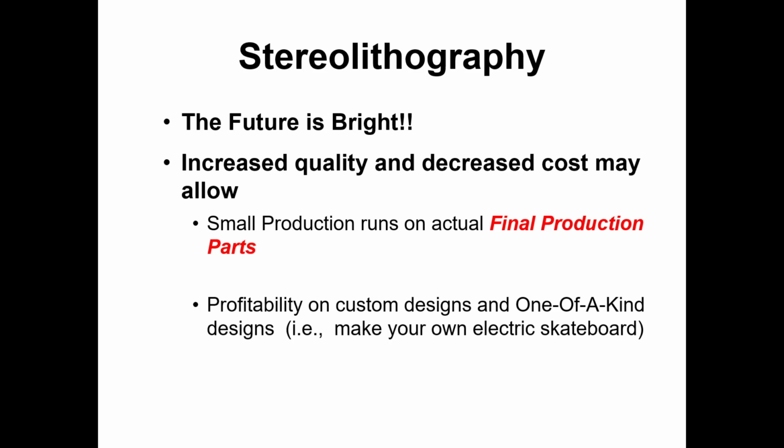But if it's a small production run, or something you just want to make for testing, or part of the product development process, where you're just handling it in the design office to get an idea of what the final thing is looking like, stereolithography is great for that. Or for hobbyists, or do-it-yourself, kind of custom small production runs. Stereolithography is awesome. It's totally cool. But if you're going to be making lots and lots of something, it's not really very useful yet.